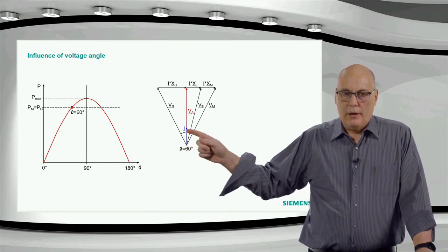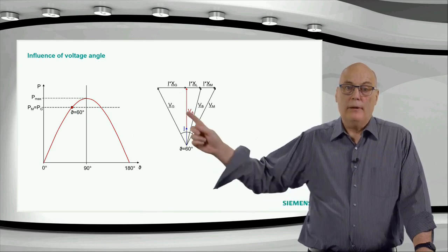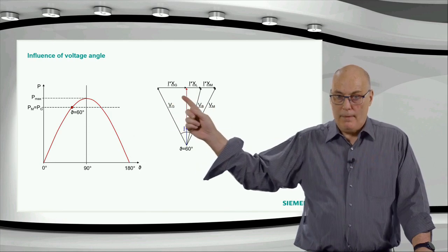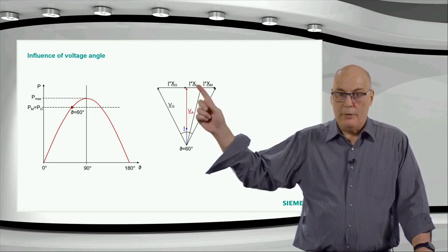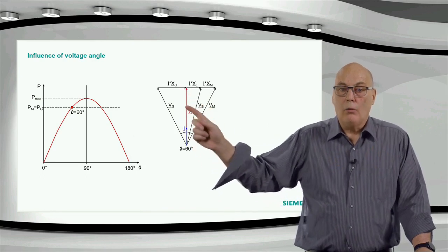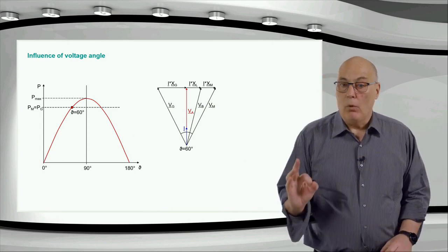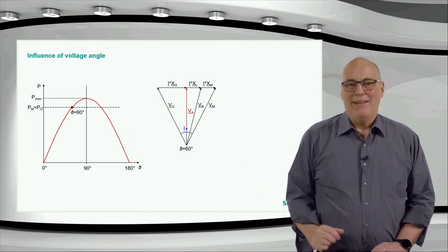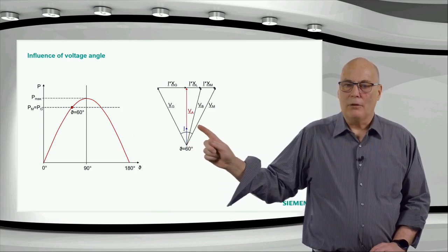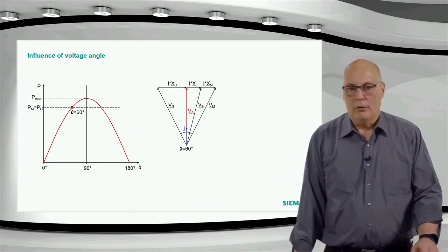Then you can see the current is shown here, vertically in the middle. The current is there in this model, and the generator is over there, the motor is over here, and the voltage drop from the generator side, the line impedance and the motor side is shown like that. The VA would be our relay location. So at our relay location, we have a pure power factor equal to 1. Current and voltage are in phase. Obviously, the power factors will be different elsewhere, because there the current and the voltage are not in phase. But here we have exactly power factor 1.